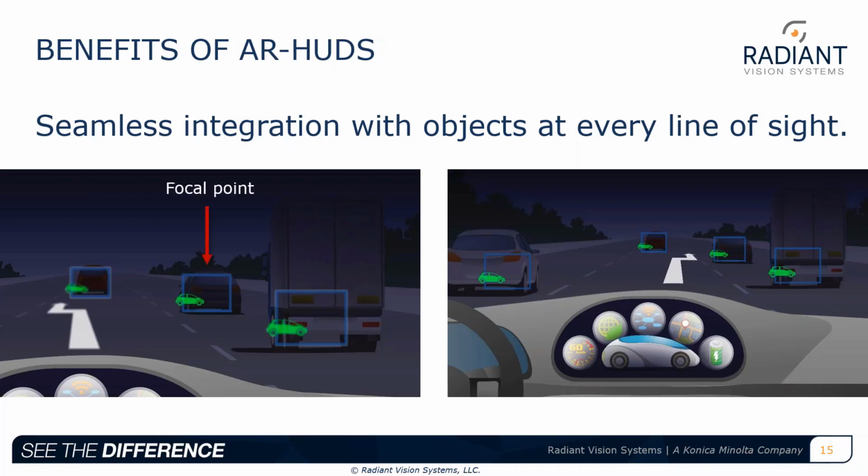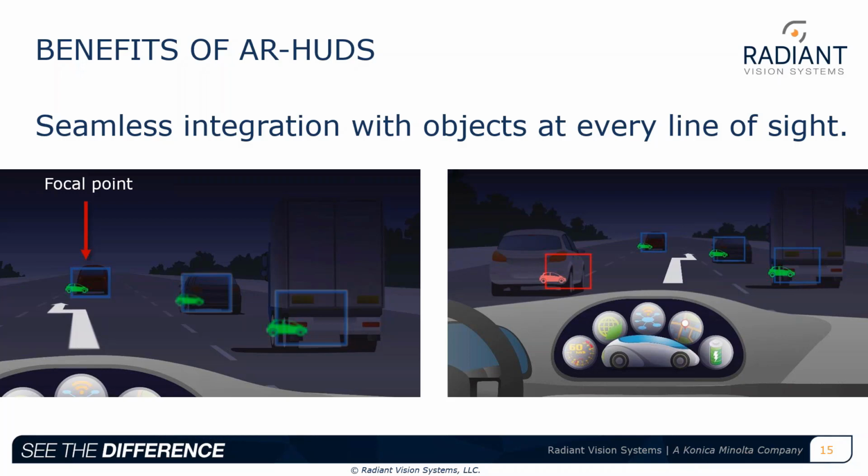The benefits of augmented reality HUDs. There are important differentiators between augmented reality HUDs and traditional fixed-position head-up displays in their ability to address focal distances and situational changes outside of the vehicle. In a traditional head-up display, all the information is static and fixed at the projected distances I previously mentioned, 2 to 4 meters. However, with augmented reality, the information is projected from 2 to 20 meters.